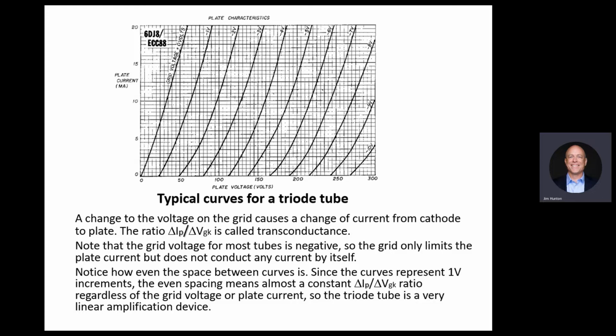No, because it will swing to negative. There's no negative current. Okay, what we're doing is basically biasing a tube. So like Tony today biased the amplifier. You put the amplifier tubes at a particular point on the chart, either here or there, whatever.